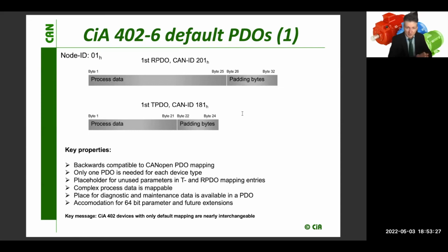So see the difference. The padding bytes are an interesting feature, and it is related more to the CAN data link layer. We don't have identification of the number of data bytes, but we have to encode their number.